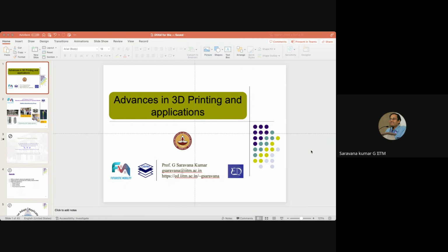So I close this session. There is one question on AIML. A lot of data analytics is coming in. Let's say you have a lot of defects while the component is being built in metal additive manufacturing. There are porosities, like keyhole porosities, and many such defects. So online monitoring and immediate corrective steps are needed, because once you make the whole part and detect the defect post-operatively, it is like a postmortem, you cannot do anything. If the component has blowholes or keyhole porosity or cracks, the component is a failed one.